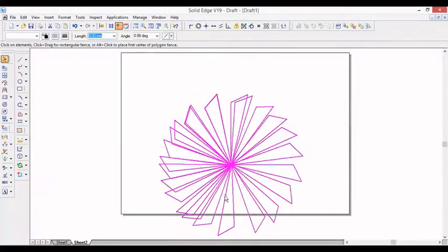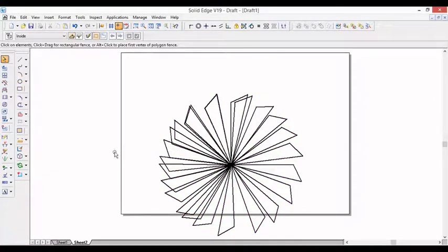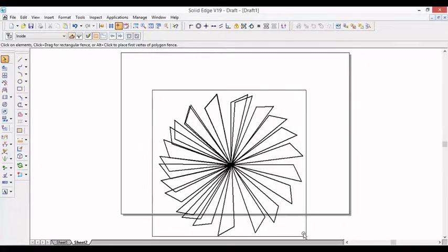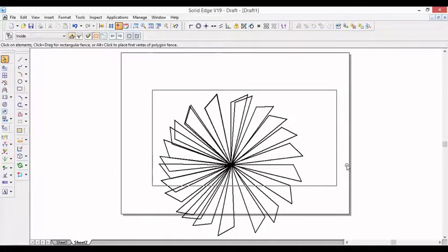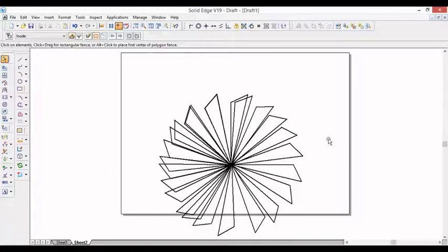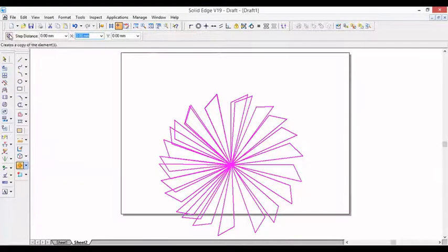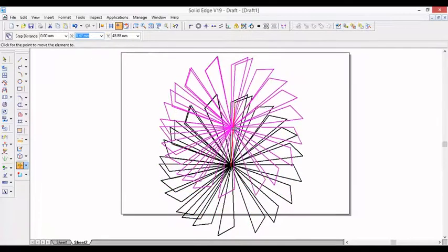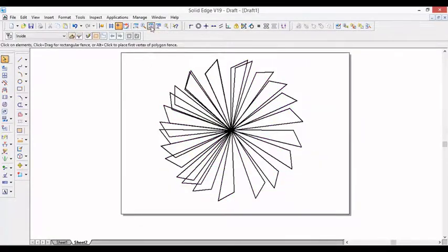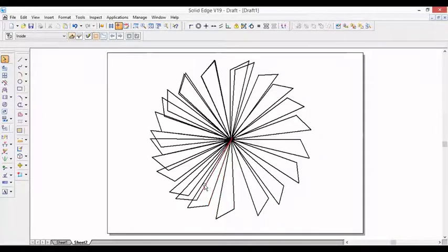And keep in mind, the drawing which is coming out of this border doesn't print. So the printable area is whatever the border mentioned inside the sheet is the limit for your drawing. So now the drawing has gone off the printable area. What I can do, I can select this and make use of the move command. I will move this with respect to the center and shift it to the center of the page. So now the drawing is inside the printable area, right?